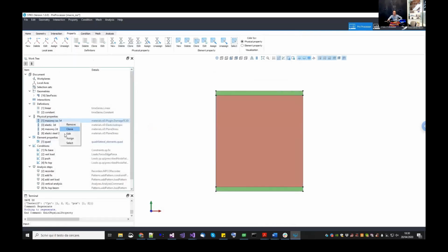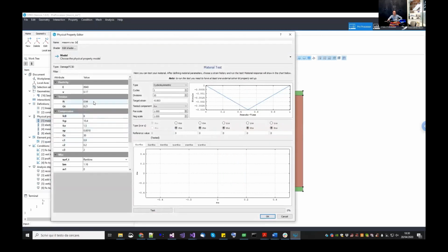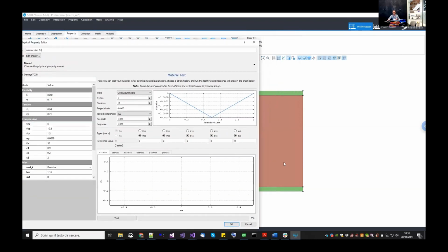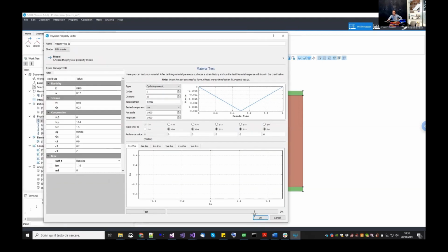direction. And in fact, you can see them from the higher tensile strength. The equivalent tensile strength along the x direction is slightly higher because you just have 2 layers of head joints orthogonal to the load direction, but then you have 2 layers of bed joints that act in shear, and this will actually increase the overall tensile strength in that direction. Of course, if you do the homogenization in the y direction, you will obtain exactly the tensile strength of the mortar joint because it is in series. Okay, so this is fine.